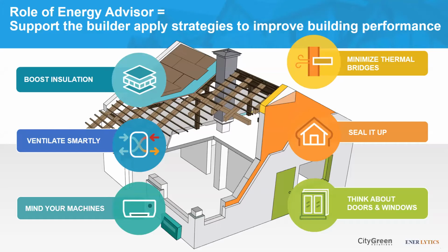Unlike the prescriptive path where builders were limited by the prescriptive checklists and options, energy advisors can advise builders to put in more insulation in a home, to use different ventilation options and very efficient ventilation options, to really focus on the machines in the home, the heating systems, and recommend the highest efficiency heating systems. There's a focus on minimizing thermal bridges, on sealing up the building envelope with airtightness and air barriers, and to really think about the window and door options available.